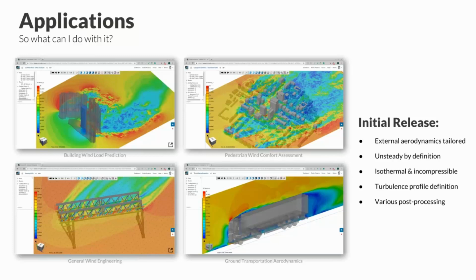We've done that in the past also with finite volume-based solvers, but it's really tough to make that economically work. If you want to use an LES turbulence model, we looked at computing times of, at times, weeks. In some situations that works, in others it's tough to economically justify. So we've always been on the lookout for a solver that provides the fidelity and accuracy that the wind engineer needs, but at the same time a much faster turnaround time.